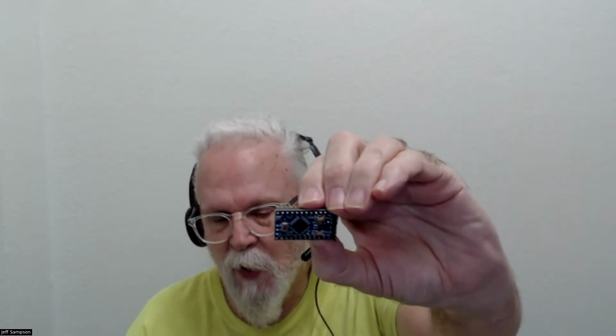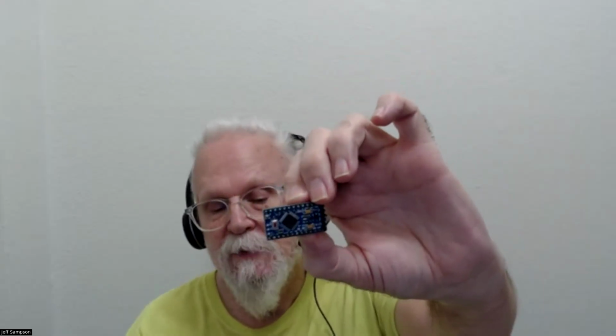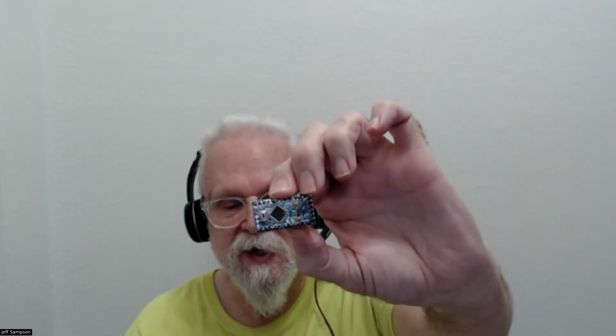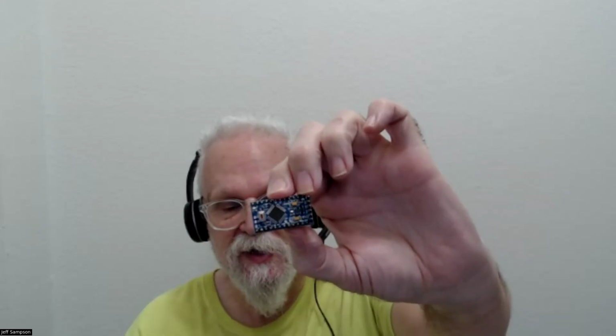And the thing would sit there running at 20 microamps, because what you do then is program your watchdog timer and say, I want you to time out in 1 second. It says they've got a command, something like watchdog timer sleep, and you specify the number of seconds, up to 8 seconds. And then it executes a sleep command. So it puts the processor to sleep. It basically just stops the clock on the processor. And since CMOS logic doesn't take power if it's not switching, it drops down. The only thing running is a counter inside to run your watchdog timer.